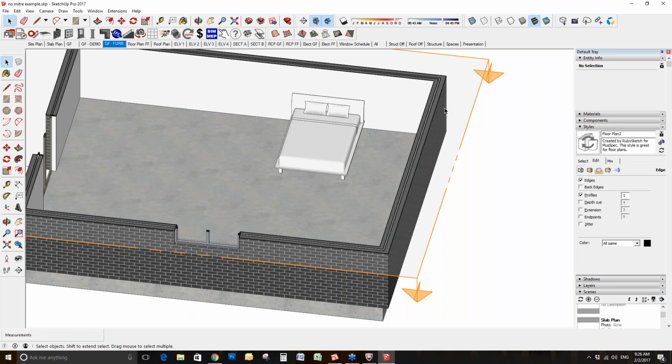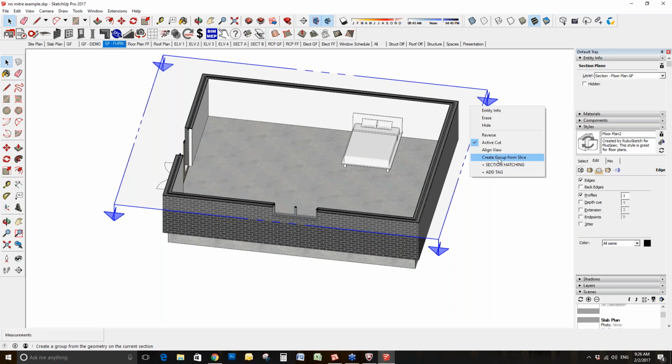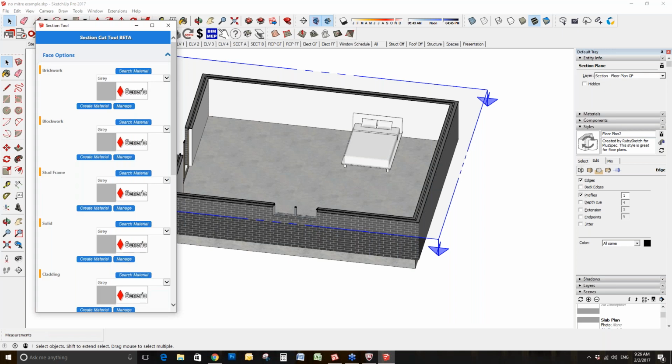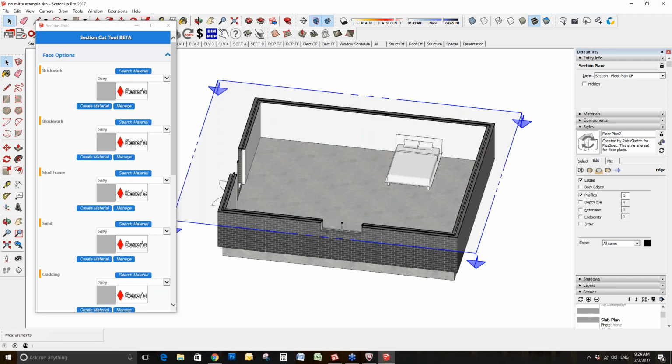What you've done is it's just a standard SketchUp section cut, or from the PlusSpec generated ones. What you want to do is just activate your section cut so you can see it. So display your section plane. Once you've done that, simply right click on it and go into now the plus section hatching. This is kind of in a beta phase. It's going to be improved and expanded upon, but it's very, very user-friendly and easy to use.